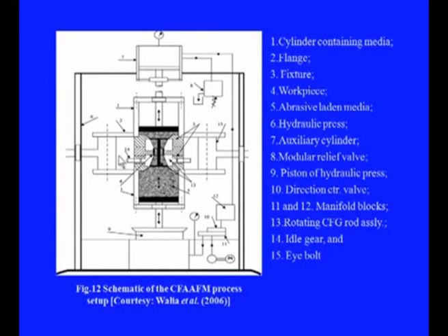This is kept rotating with gear devices, which are connected through this tooling arrangement, and the speed of this rod can be adjusted according to the requirement. Because of the introduction of this rod, the pressure inside will be enhanced, the restriction will be more, and therefore the effect of these particles on the finishing of the workpieces will be much more.